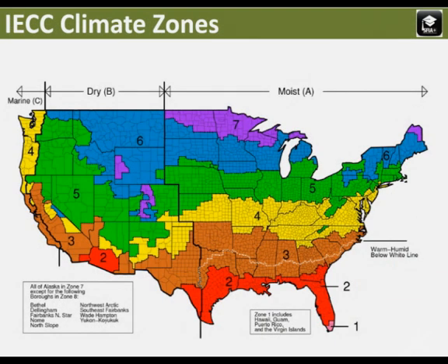With the R-value prescriptive approach, we first will reference the climate zone map in Chapter 3 of the IECC. For example, Tampa falls into the red section, or Climate Zone 2. Cleveland would fall into the green part of the map, or Climate Zone 5. In our example, Richmond falls into the yellow area, or Climate Zone 4.